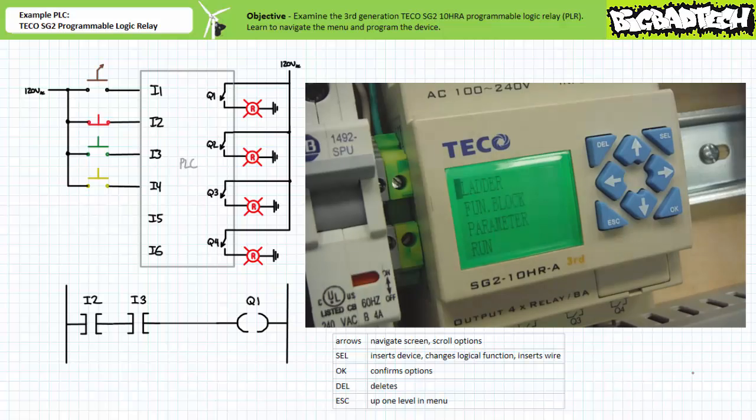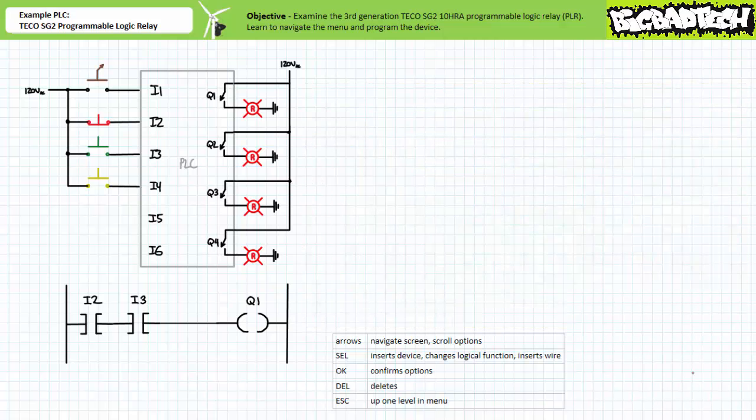Before we place this PLC in run mode, let's take a look at our sample system again. Note our program only uses inputs 2 and 3 and output 1. Let's ignore the other devices and concentrate our attention only on these devices. Note the field input device attached to input 2 is normally closed by nature, despite it being instantiated in the PLC program as a make instruction. Remember, the electromechanical nature of a switch's deactivated state has absolutely nothing to do with how that input is logically instantiated in a PLC program.